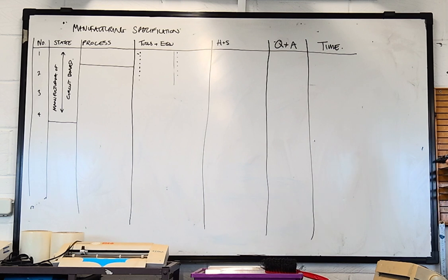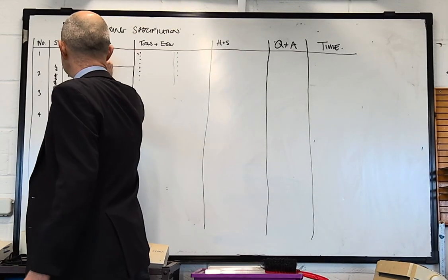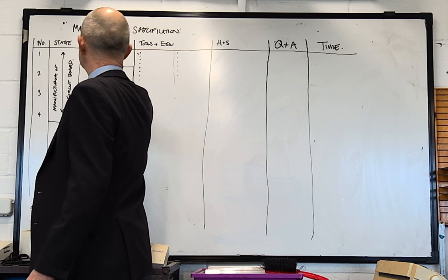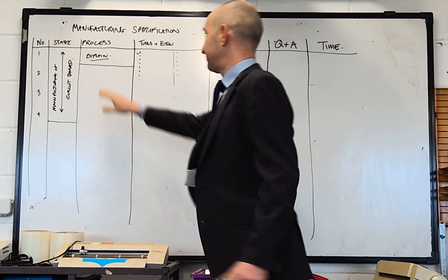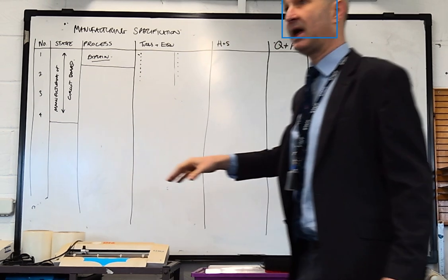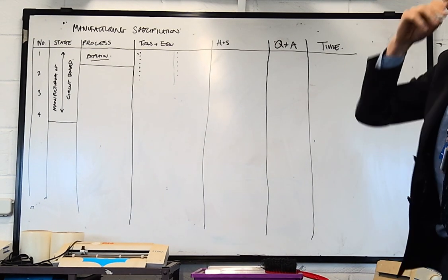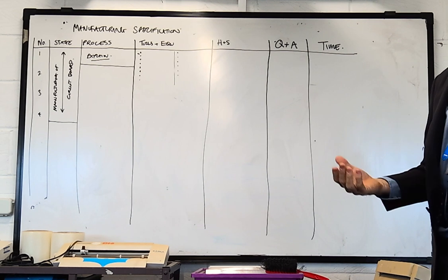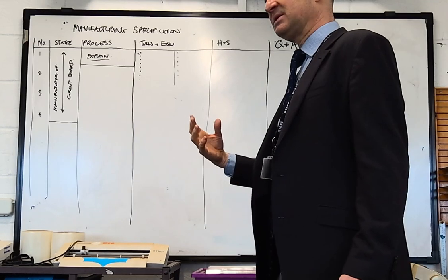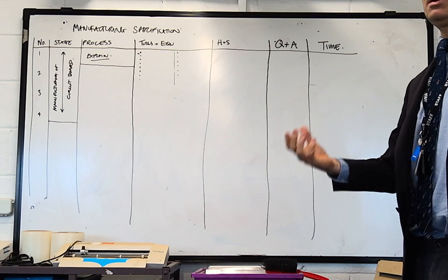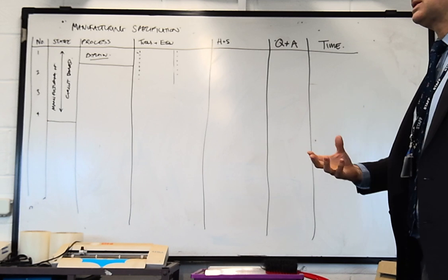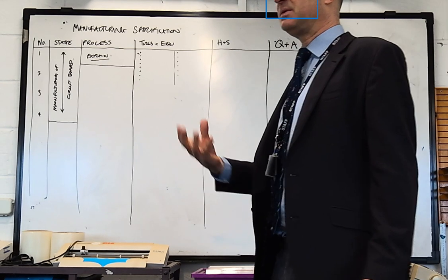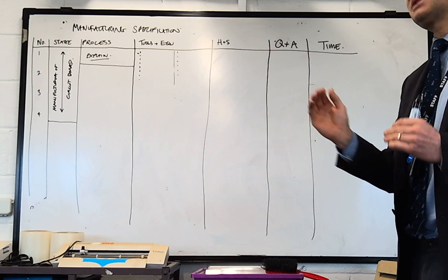Yeah. Good? Casey, you're looking a little bit confused here. This is like an explanation. So explain the process, yeah? This is a list of the tools and equipment that you're going to use. I'll go back and do it again. So for this, for example, you may write something like, for this process, I am going to begin creating my circuit board. To do that, I'm going to take the CAD and print my mask on a transparency. Once I've printed it on a transparency, I'm then going to use that transparency to project the image onto a piece of PCB. That to me probably sounds like 2 steps, to be honest with you.